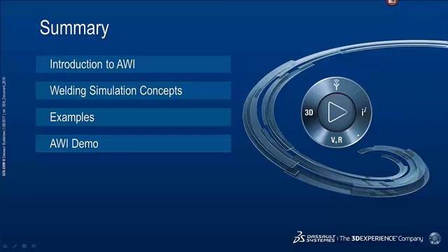But as soon as it becomes active, typically there is a big differential in the stiffness, and so if you're not careful, you will end up with a discontinuity in the stress. So our methods now address that discontinuity and make sure that the jump in the stress magnitude is avoided. We do all that at an increment level without having to switch to a different step, which was the case for model change. Okay.